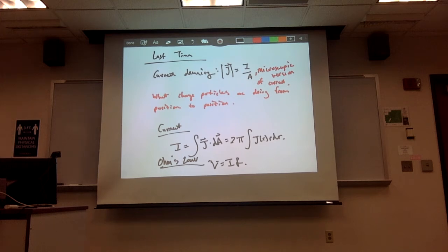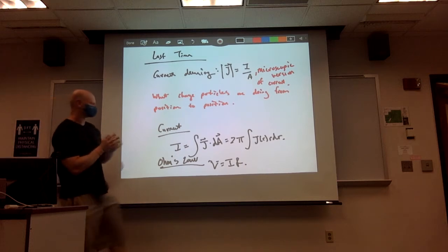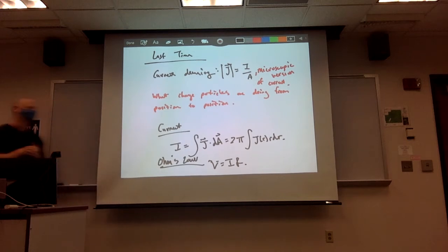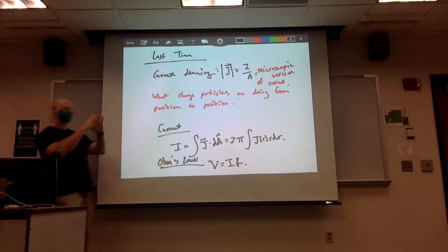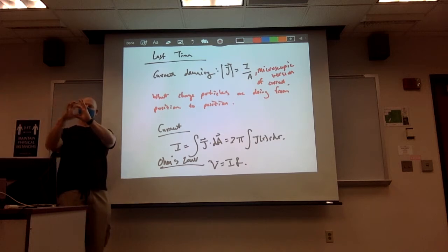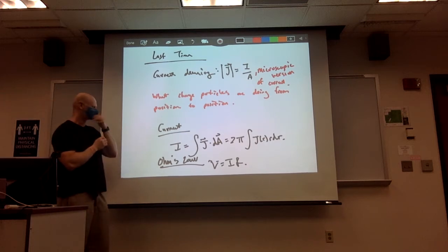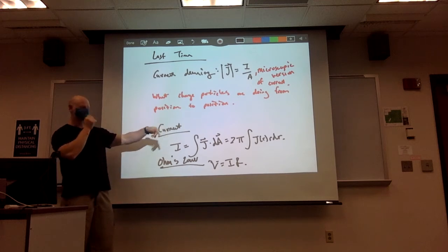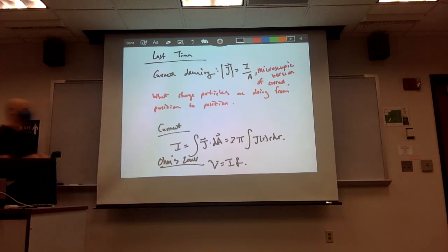Primarily wires, but in this case it depends on what the profile looks like. That means we can find the current from the current density by averaging the current density over the entire cross-sectional area of this particular electrical element, or our wire in this case. For our purposes we're always looking at a wire, so it's a cylinder, and the differential cross-sectional area is 2 pi r dr.